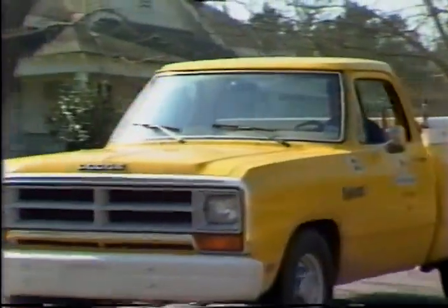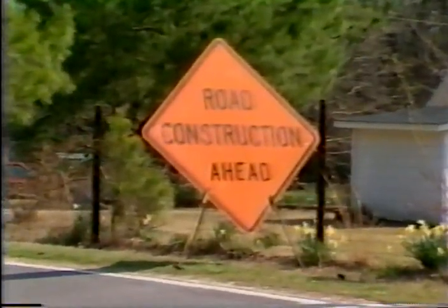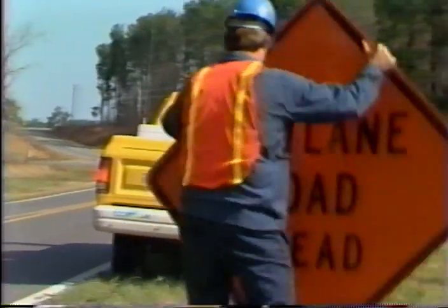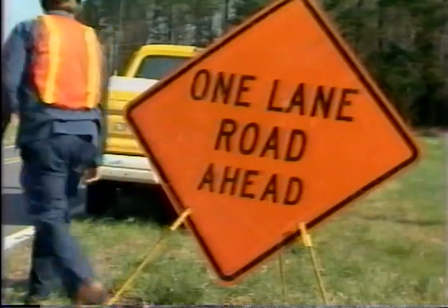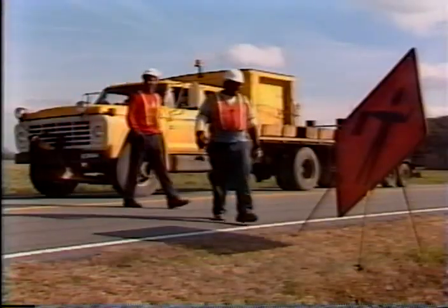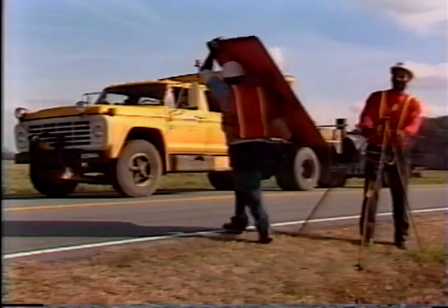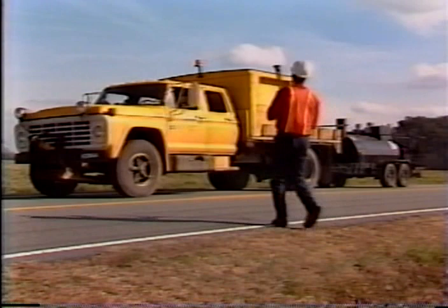Drive through the work zone prior to beginning maintenance operations to be sure that traffic control devices are properly placed. Periodically during the operation, check the traffic control devices to be sure that they are still visible. When the maintenance operation is completed, remove the traffic control devices. Remove the signs in the reverse order in which they were placed.